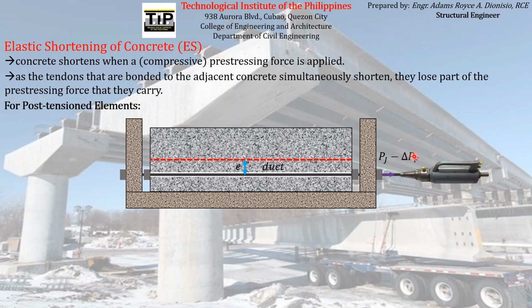So we will not be concerned with that for this particular topic, but we are concerned with the pre-stress loss due to the elastic shortening of the concrete at this particular stage of pre-stressing. So after the pre-stressing reinforcement is cut, again, the pre-stressing force will be transferred to the concrete element with a magnitude equal to the jacking force less the pre-stress loss due to friction. But